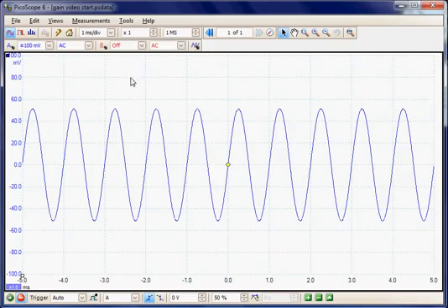Before any tests can be performed, the amplifier or device under test has to be set to a known condition. So for example, the bass and treble controls have to be set to flat and any loudness controls set to a known state, so a calibrated test can be made.